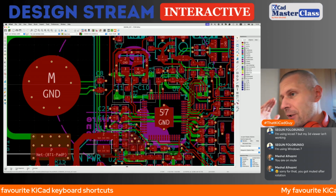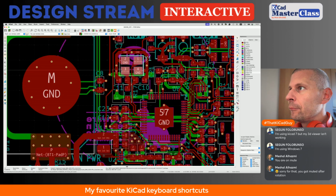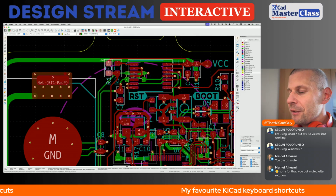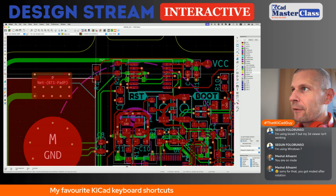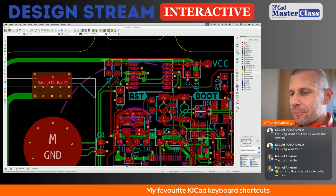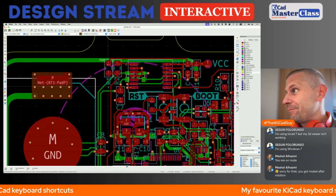Very, very smart thing. Move item, of course. M is the rough movement without the design rules. D is dragging with rerouting the routes, but frankly, between us, it almost never works. It doesn't work.